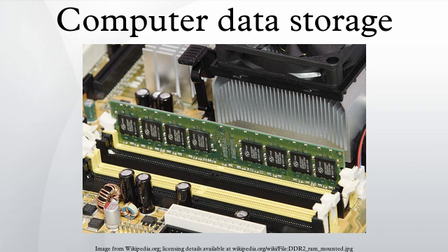Phase change memory uses different mechanical phases of phase change material to store information in an XY addressable matrix, and reads the information by observing the varying electrical resistance of the material. Phase change memory would be non-volatile, random access read-write storage, and might be used for primary, secondary and offline storage. Most rewritable and many write-once optical discs already use phase change material to store information.